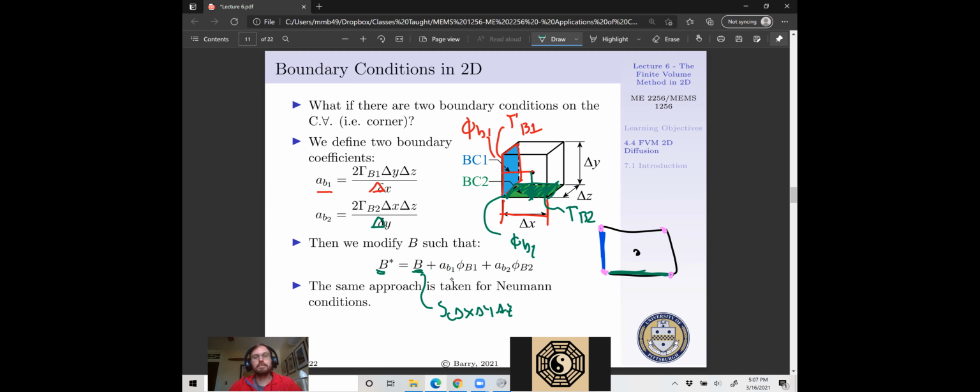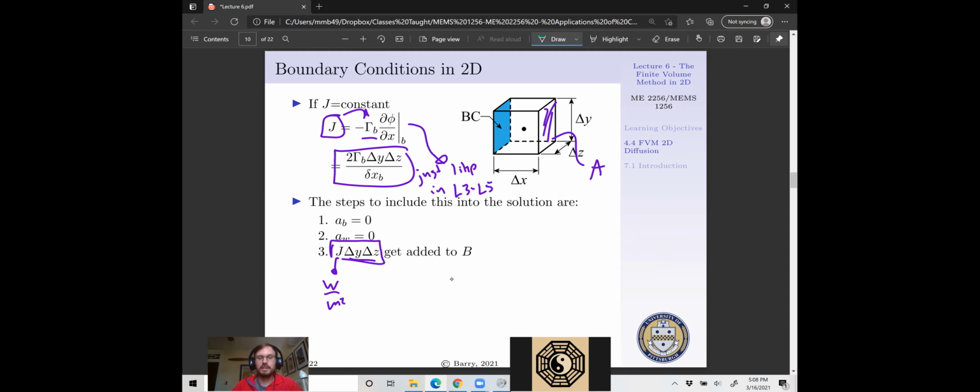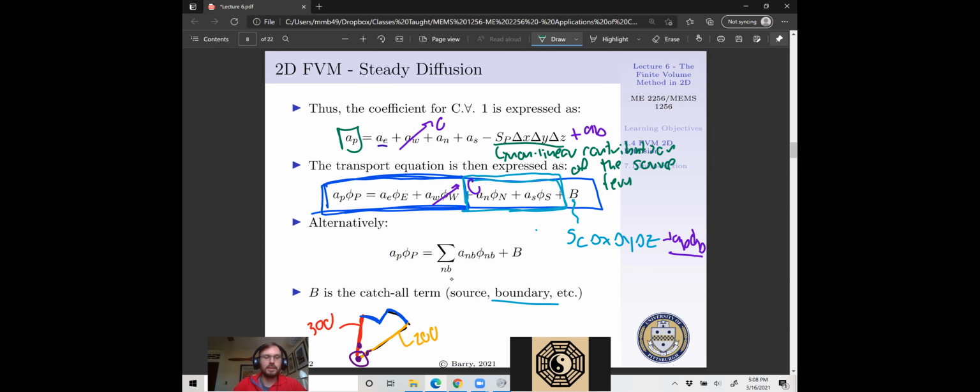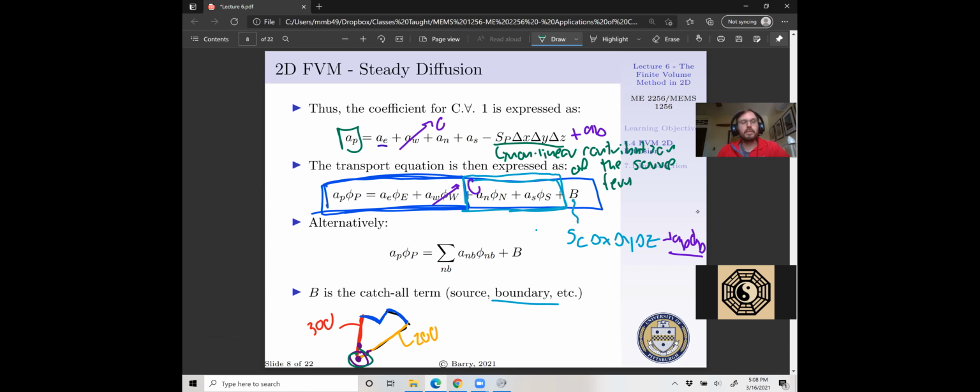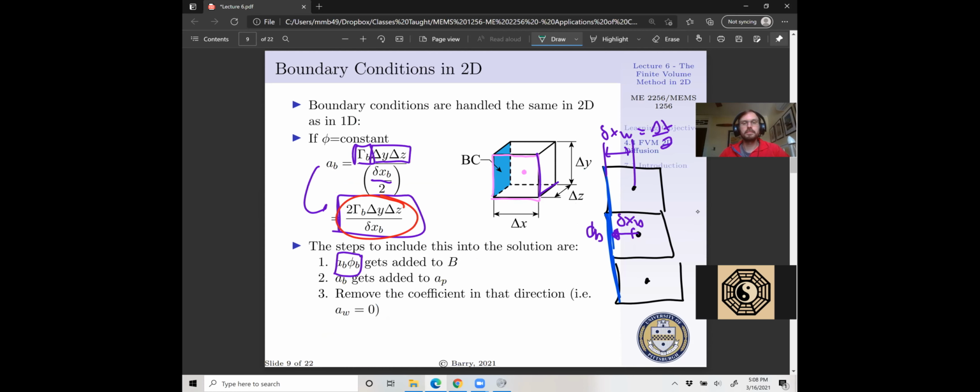you get into problems with pie-shaped slices like this. Any axisymmetric problem, if you're not doing the whole revolution, it gets really tough. So sometimes it doesn't allow you to capitalize on the symmetry of the problem.